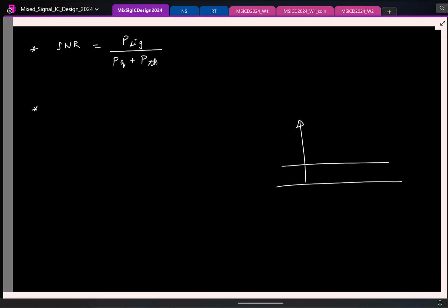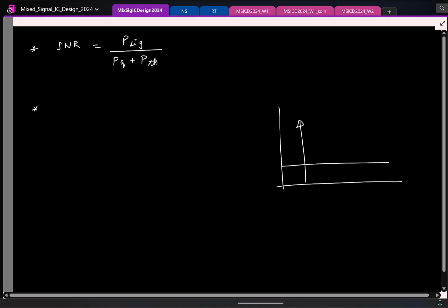In addition, if the circuit is non-linear, what do you expect to see in the spectrum? So which means, distortion in the spectrum, you will see the harmonics of the input sinusoid. So we will see second harmonic, third harmonic, and so on. Right? So the output will no longer be my input plus quantization and thermal noise. We will also have, let us say, alpha 2 y squared, some alpha 3 y cube, and so on.